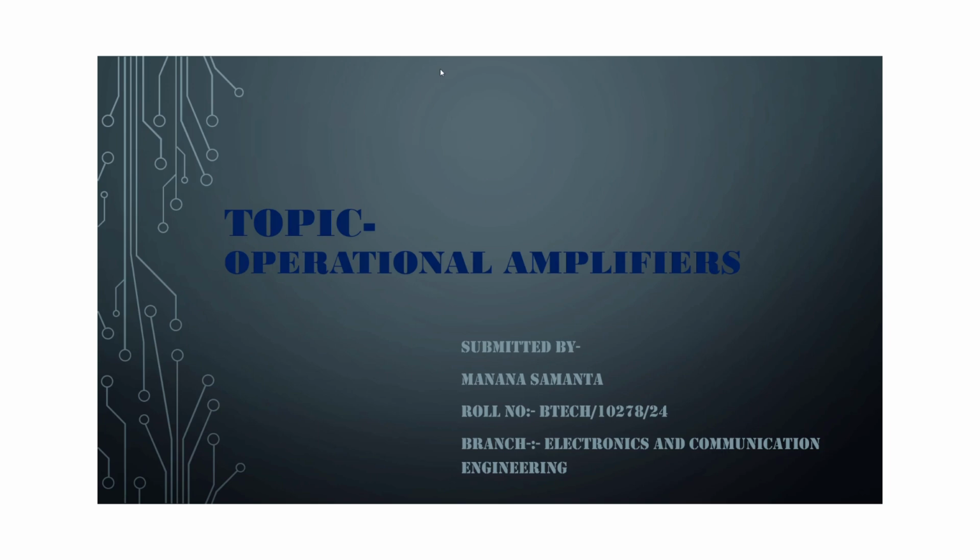Today I'm going to discuss operational amplifiers. The operational amplifier, Opamp, is a direct coupled amplifier with a very high voltage gain, very high input impedance, and very low output impedance. Originally, Opamp was designed to perform mathematical operations such as summation, subtraction, multiplication, differentiation, integration, etc. in analog computers. That is why it is called operational amplifier.